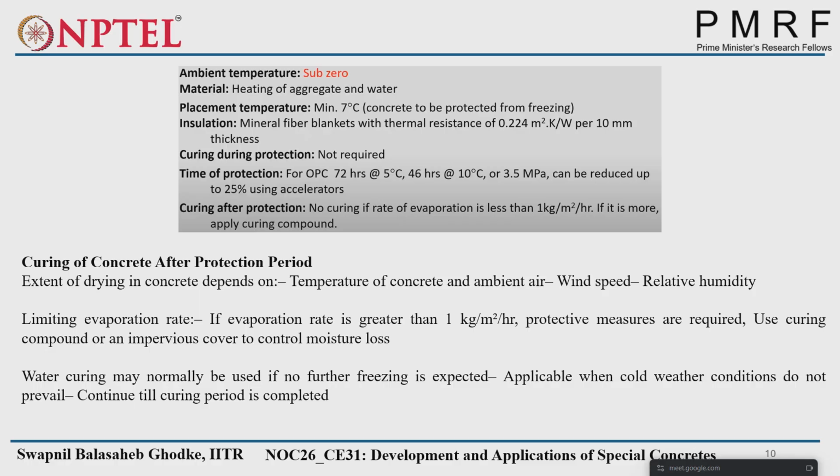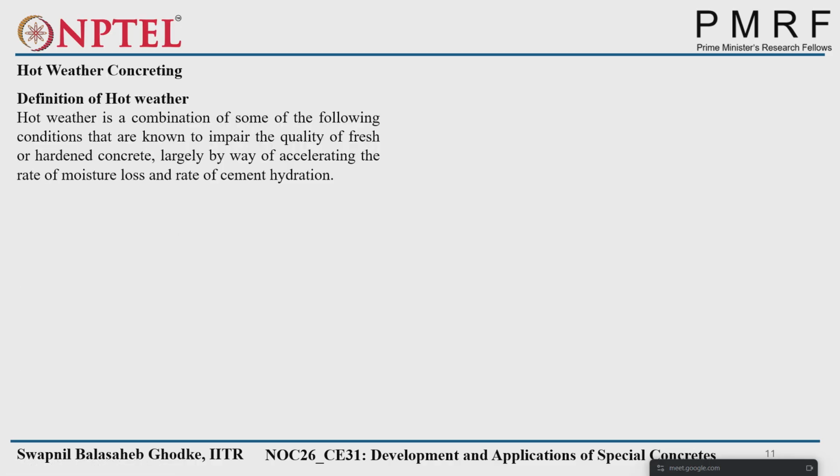Water curing, as we say here also, if it is required and if freezing conditions are not there, we can use water curing. Otherwise, we cannot use water curing. So this is the cold weather concreting.